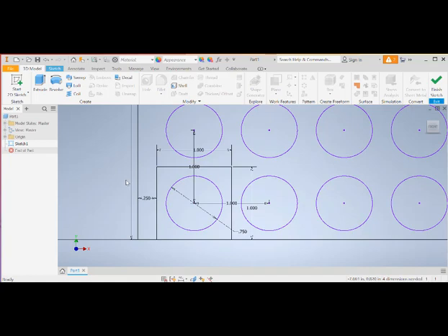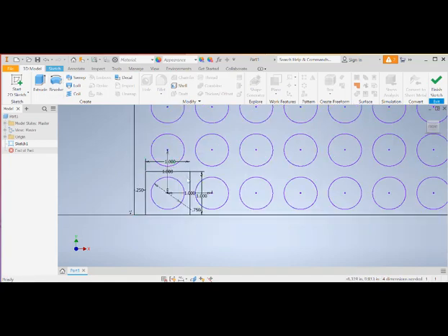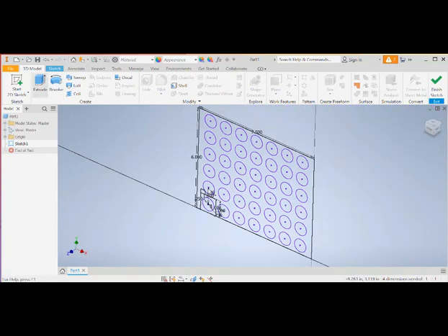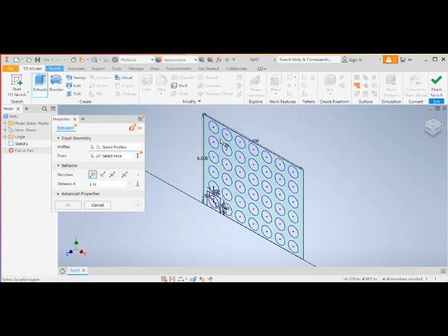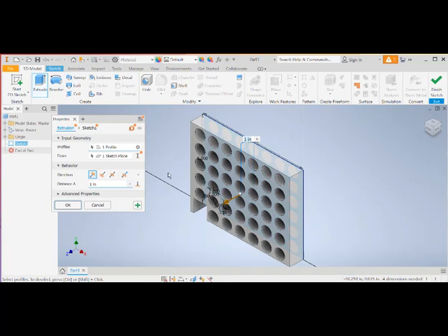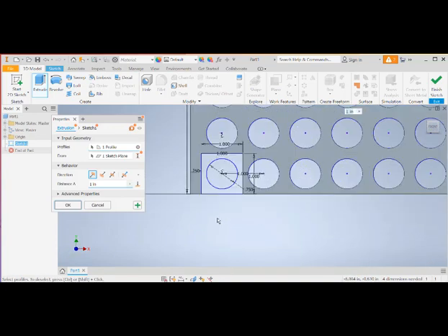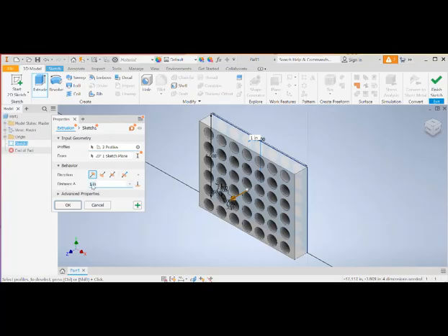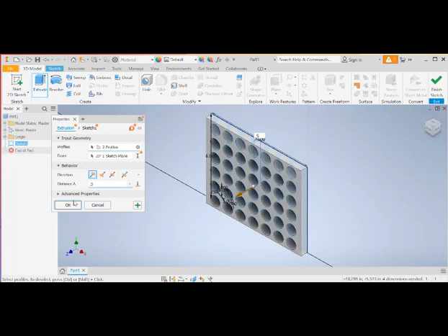So ignore that. I have to make sure that when I extrude, I grab all of the correct area. So I don't want to extrude the circles. I only want to extrude the base frame. But notice that I didn't get that area within the square. So I'm going to zoom in and say, nope, I want this too. And I had decided that mine would be a 1/2 inch in thickness. So my extrusion is 1/2 inch.